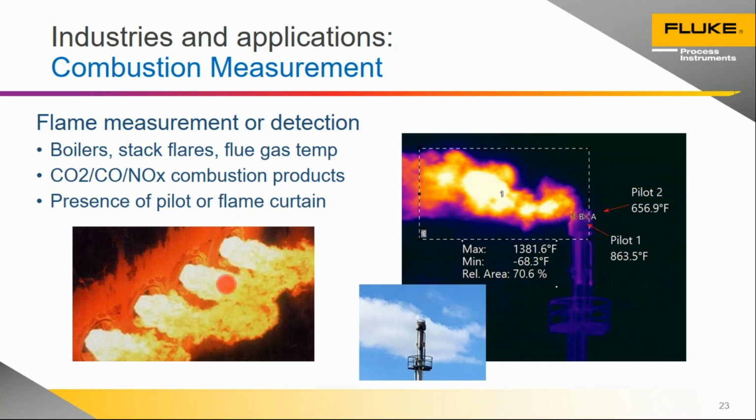And this allows us to actually make temperature measurements of the boiler itself, stack flares, the flue gas temperature as it comes up out of a furnace or a boiler. And in these cases, primarily the goal is to make sure that you have efficient combustion and that you don't have emissions that are beyond the regulations that these plants have.